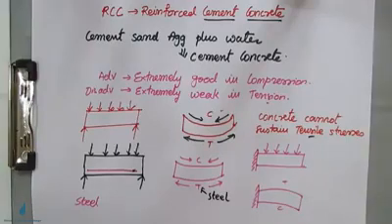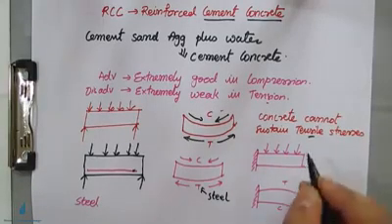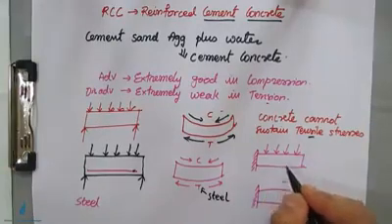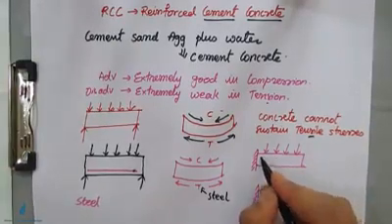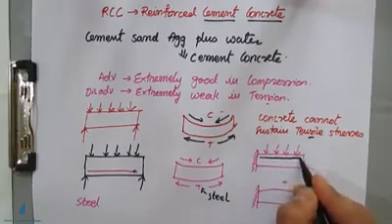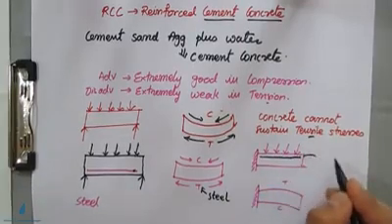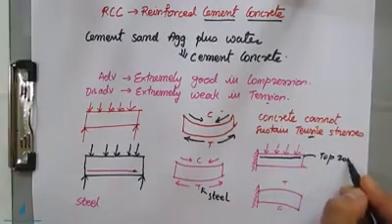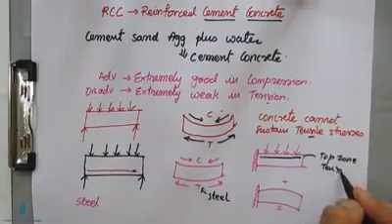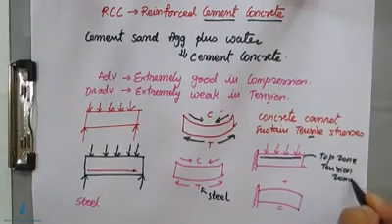You have to reinforce the steel in the tension zone, and in the cantilever case the tension zone is in the top fiber. So you have to place the steel at the top zone, or tension zone, right?